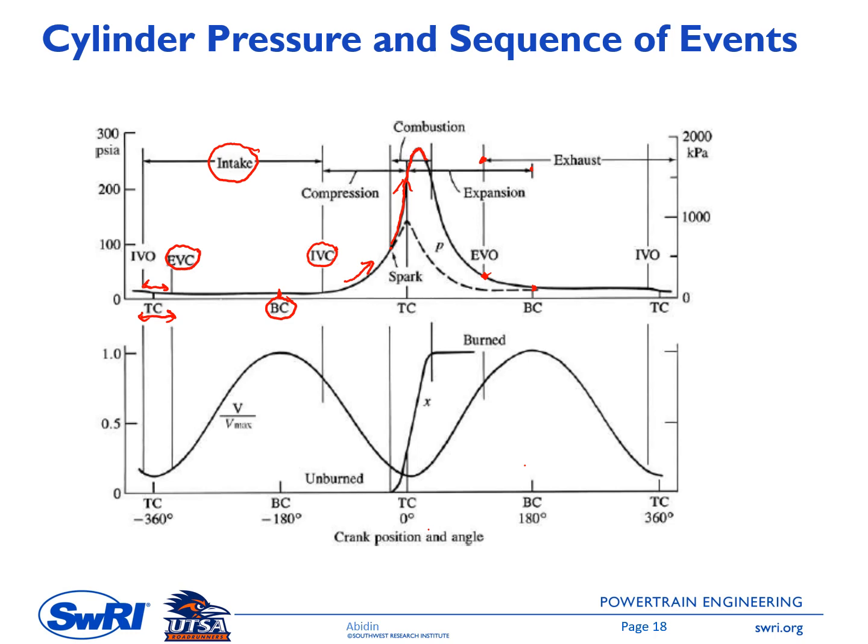Okay, until this point. So what happens with the cylinder pressure if we don't have a combustion? It is shown with this dashed line. If we don't have the combustion, the cylinder pressure still increases because of the compression, but the peak cylinder pressure will be only at this point. This cylinder pressure with the dashed line is usually called motoring pressure.